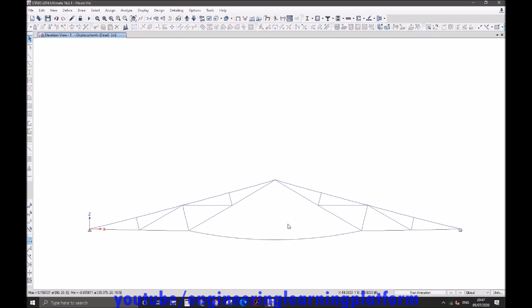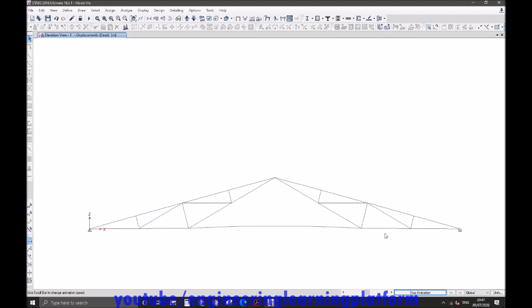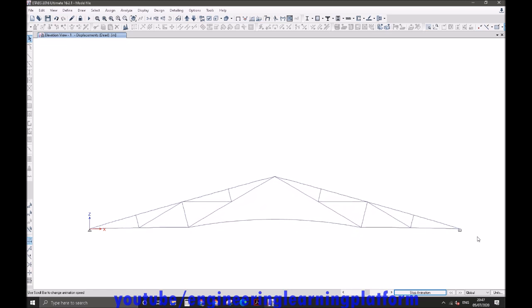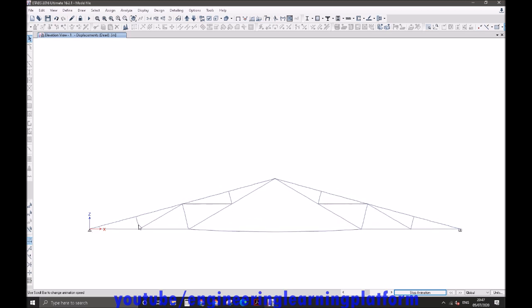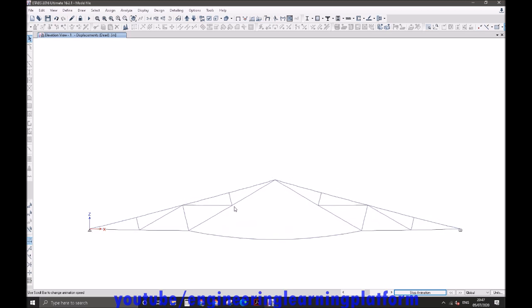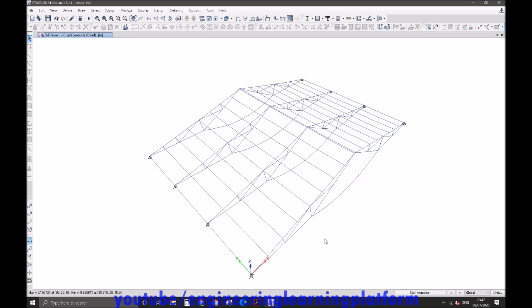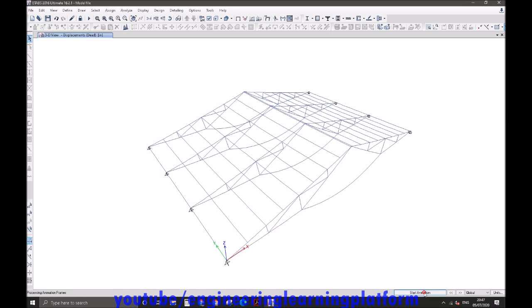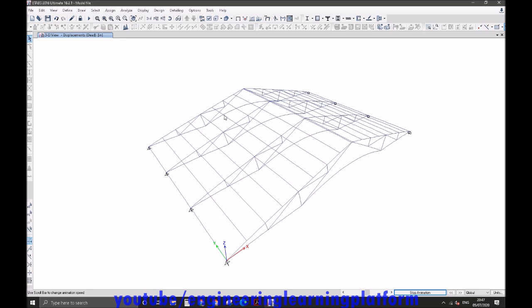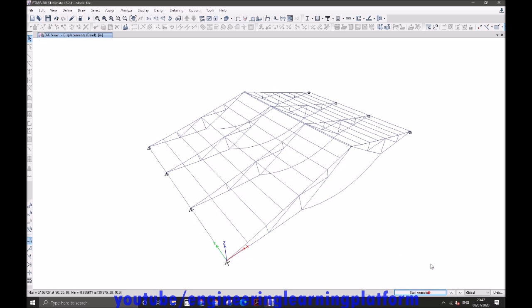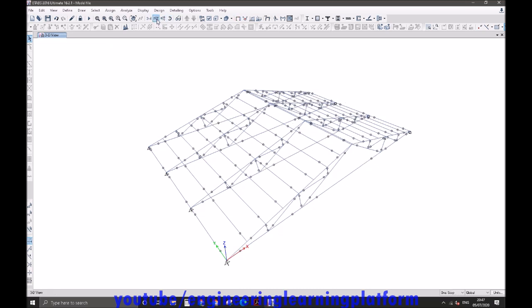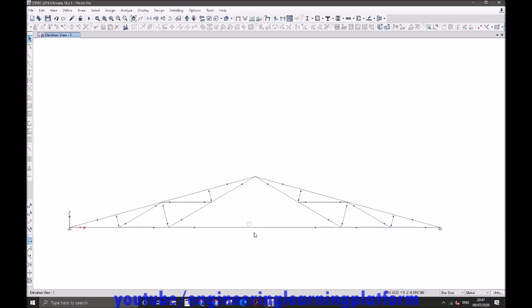Let's run the analysis and then the design. First we'll check whether all joints are properly modeled. This joint is properly modeled, no disconnectivity or irregular deformation. Similarly with the other joints, they are properly connected. Turn off the horizon. I don't usually prefer to work with it. It confuses the lines. So the bottom chord is basically going under the largest deflection, which is, I suppose, reasonable.